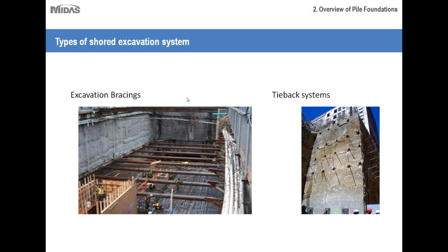And then here we have some examples of deeper excavations for larger scale structures. As you can see, these excavation bracings here support the wall to brace against the soil pressure that's acting against each of these walls. We'll talk more about the soil pressure and how to account for it later on in the presentation. And then also here we have some tieback systems, where you can drive steel reinforcements into the soil walls and tie them back here at the end. And we'll discuss how to model these as well in numerical analysis.